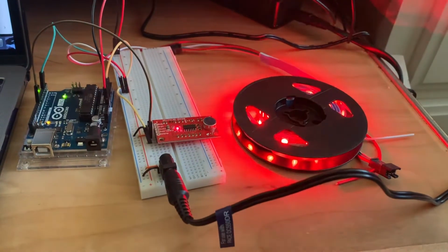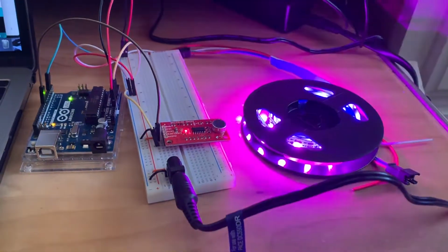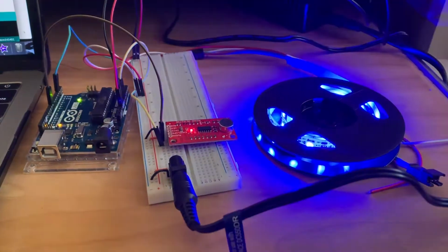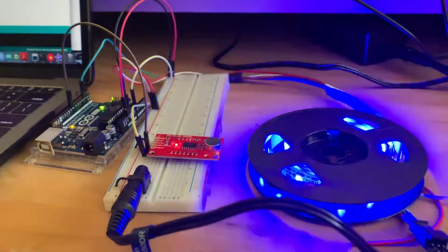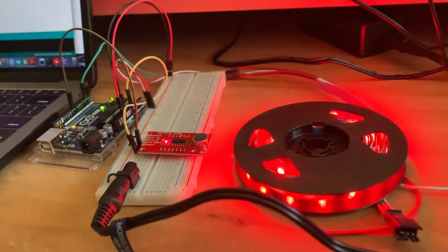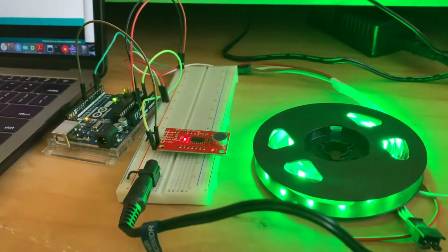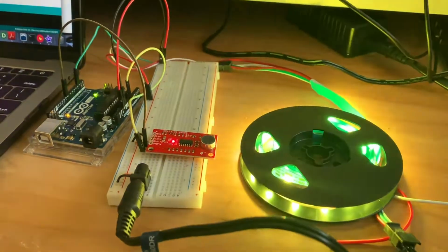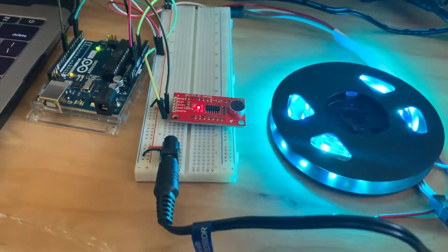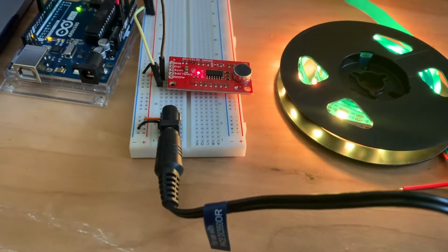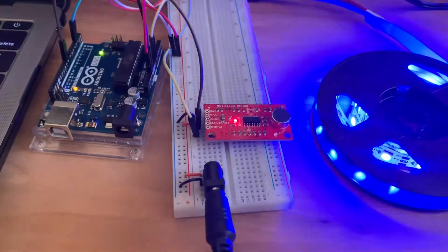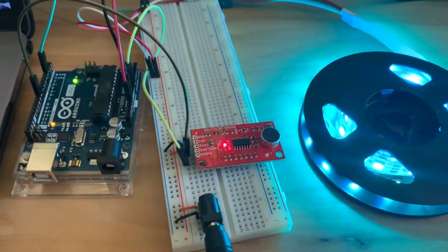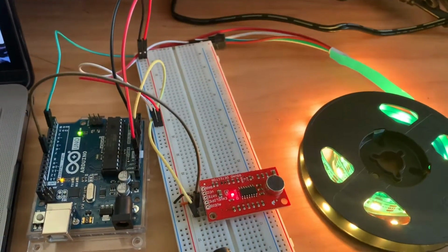Now, the device works in the following way. First, power is fed into the 5-volt power port via the 5-volt power supply. I ordered one off a SparkFun which plugs right into the wall. Note here that everything shares a common ground and that 5 volts is enough for the Arduino, the microphone, and the LED strip. Though the microphone has 4 total outputs, I only use 2, the gate and the audio.